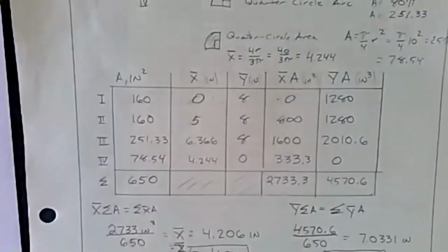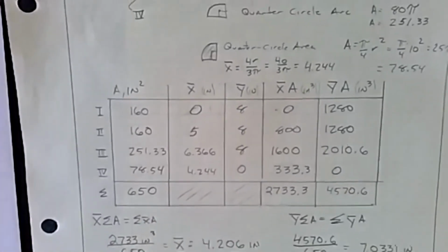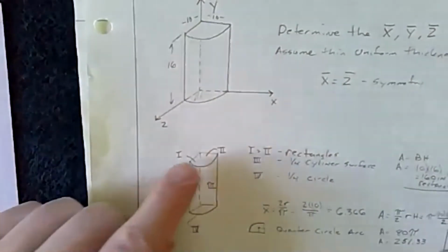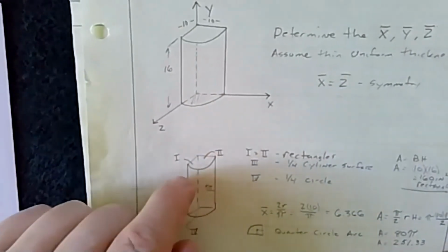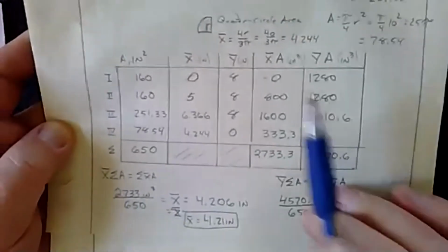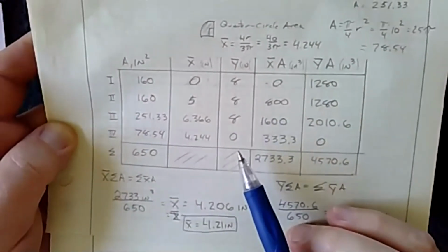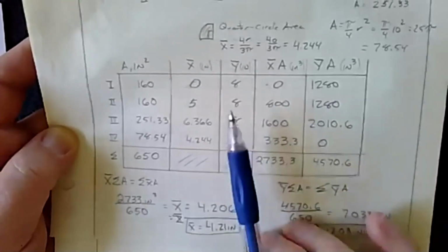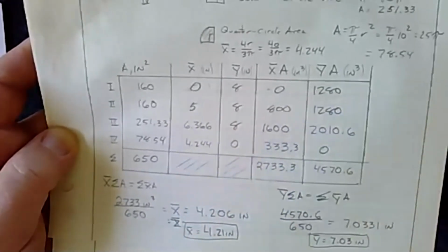I don't need Z bar since it's symmetrical. So then it's just the Y bar. And so Y bar is easy. From the height standpoint, it's just halfway up. And since it's 16, we know halfway up on 1, 2, and 3 is all 8. And then 4, since it's right at the origin, it's going to be 0. So you come back to that, 8, 8. So go ahead and multiply through like before, and that's the easy part. Once you get this, the rest of this is just rote math.